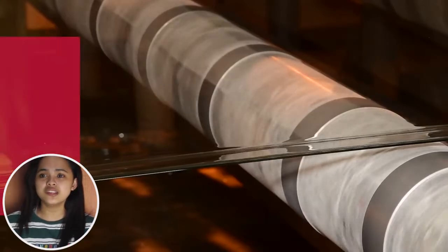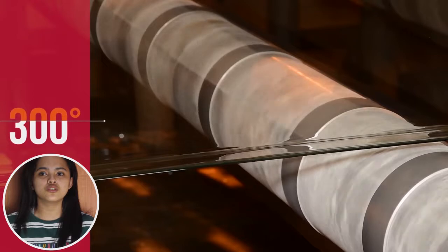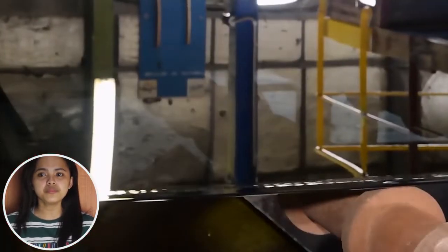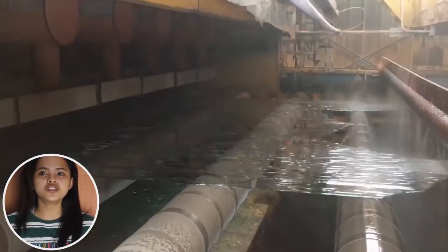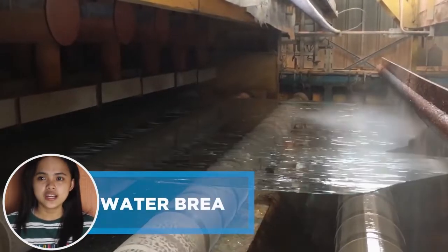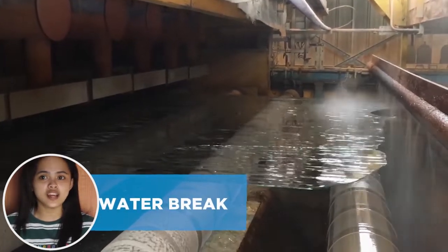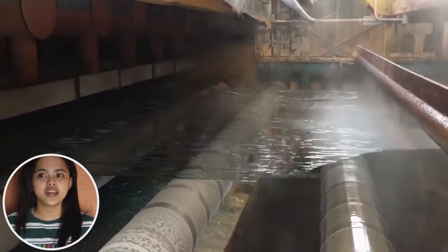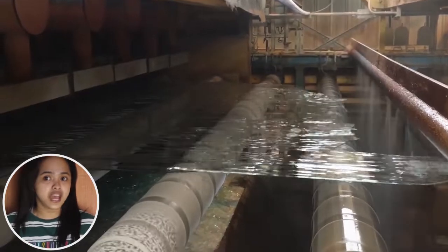At about 300 degrees Celsius, it becomes possible to lock out the downstream area of the line without impacting its upstream part. This can be useful for maintenance purposes. For instance, the operation, called water break, consists in sprinkling water on the surface of the ribbon to create a thermal shock effect that causes the glass to crack and break. Past the water break point, the lehr is not covered anymore.